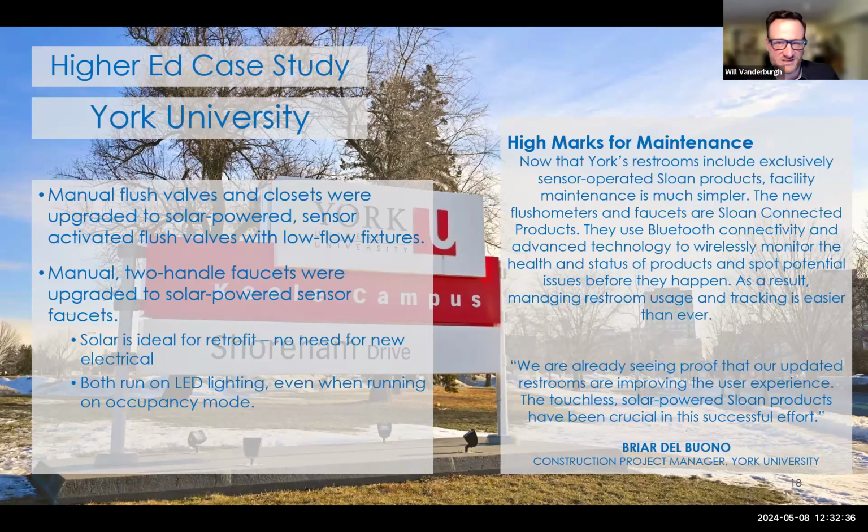And then their manual faucets have all been eliminated and they've gone to sensor activated solar. So the solar allows for much extended battery life, 3 to 4 times the life that you would find. A lot of the same benefits that you would find with hardwire technology, except now you haven't had to run new electrical. So now it's a single trade installation. A lot of universities I found in Ontario particularly are quite fond of anything that they can do to make plumbing a single trade installation or maintenance.